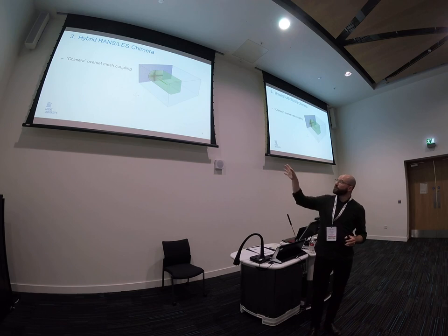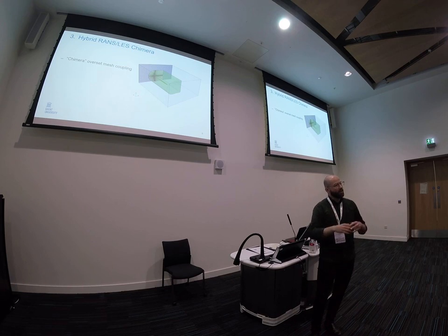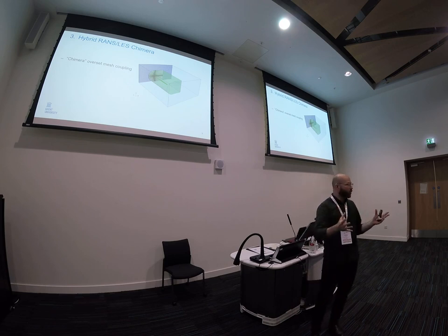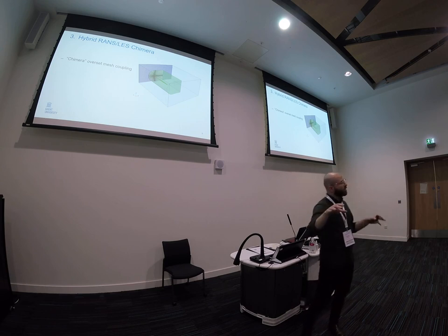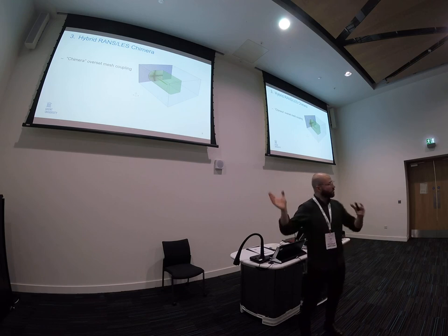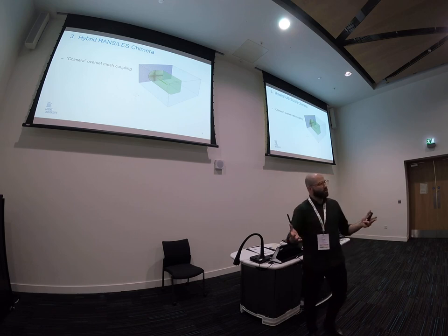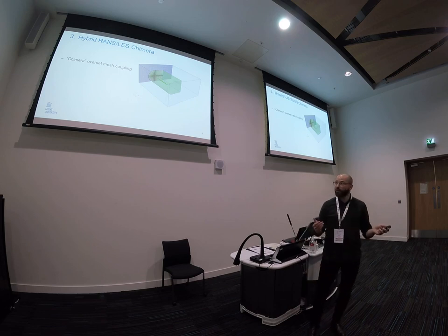We have, for instance, in green our wing, and around this wing we build our overset mesh, or component mesh, that we want to refine quite finely in order to capture this local aerodynamics. So we focus mostly on this region of interest around the kite. Around this box we can then build our background mesh. Here in this picture it is shown relatively small, but this is a region that we can easily increase in size to capture maybe larger parts of our flight path.